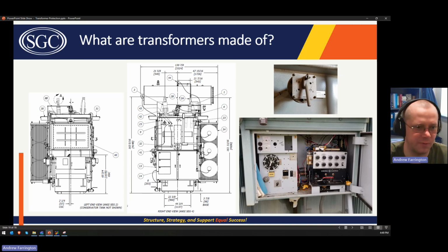You can have a VT that's feeding this thing 120 volts, and it sets the band center at 120 volts, and then there's a bandwidth of, say, 4 volts. So you can go down to 118 or up to 122, but if it gets outside of that area, this LTC controller will detect that and then automatically change the LTC position to keep it within that band. So that's the theory behind that at a super high level.